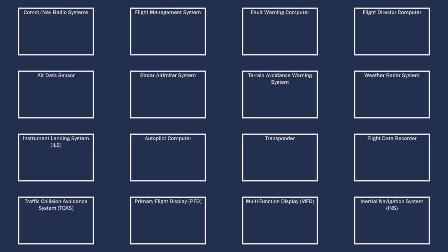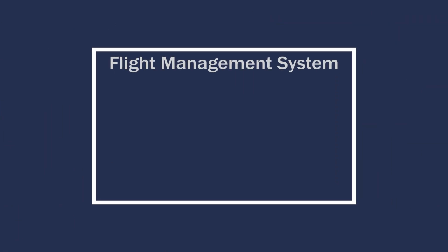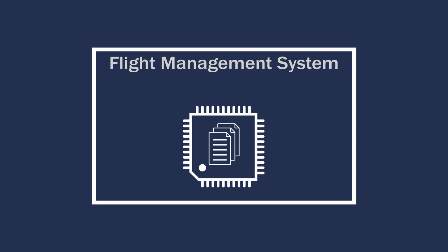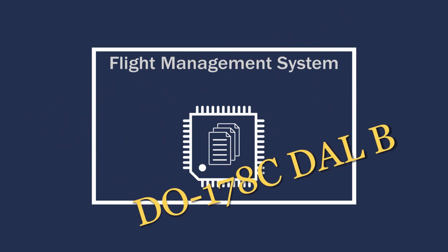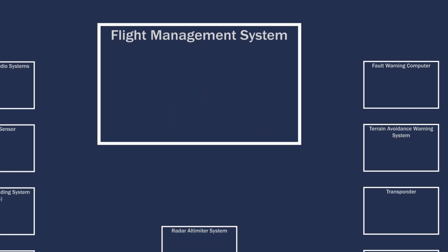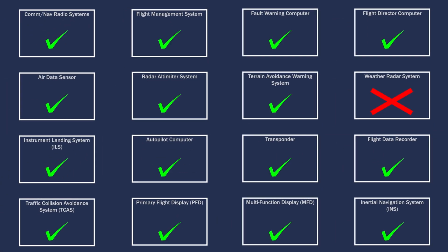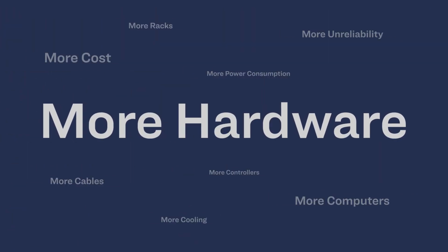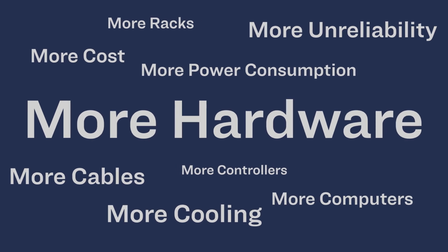In the past, aircraft were built using federated systems. In other words, each functionality would be deployed using one physical box. Each box, composed of software and hardware, is certified as a complete module to a certain assurance level, and this kind of certification was relatively inexpensive. A failure of some kind of functionality would be limited to the box that function is housed in. However, the problem with this approach is the need for more hardware. More hardware means increased weight and increased power requirements.